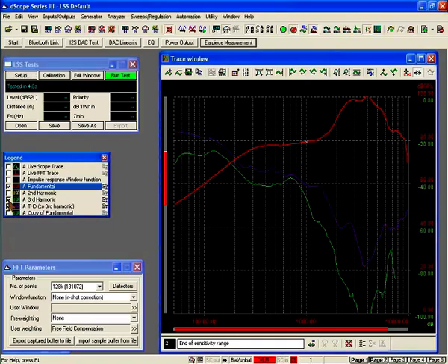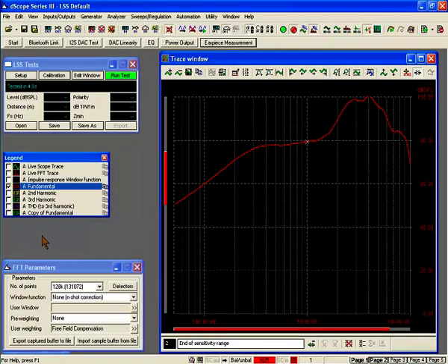Well, those of you who perhaps haven't measured a headset before, maybe more used to measuring loudspeakers, this frequency response looks a little bit unusual. We've got quite a large resonance here over the 2 kHz to 6 kHz region. This in fact is down to the ear canal resonance in the ear and cheek simulator fixture that we're using here in the demonstration. So this is what actually happens in your ear, but you are psychoacoustically adjusted to this, and this doesn't sound like a huge great resonance that you might expect it to sound like if this was actually originating from a loudspeaker.